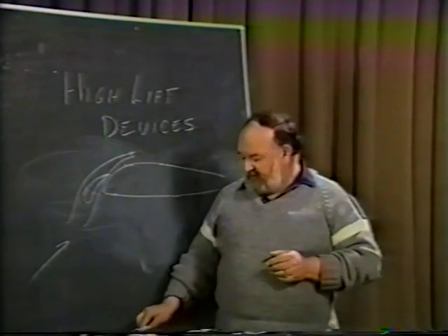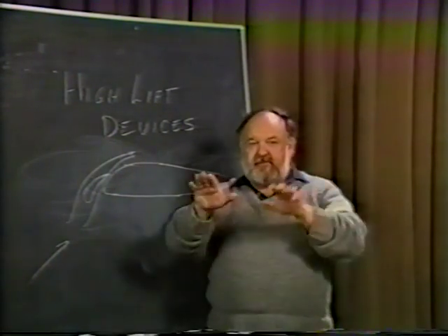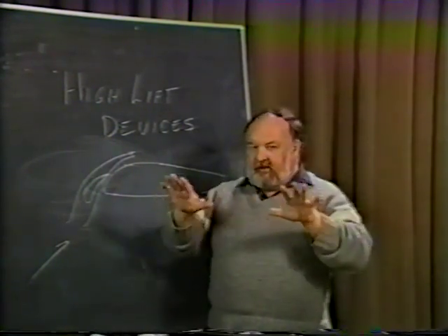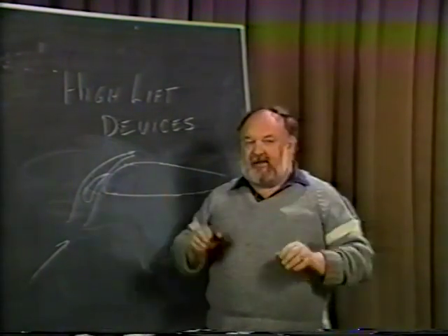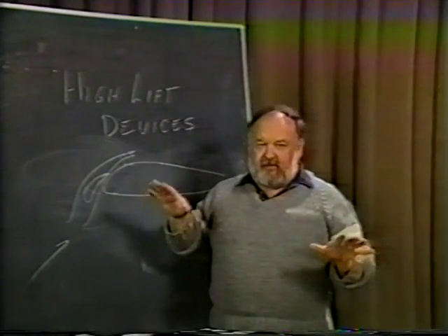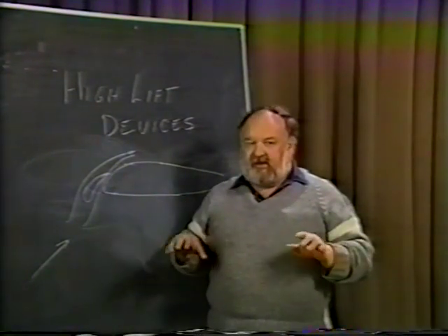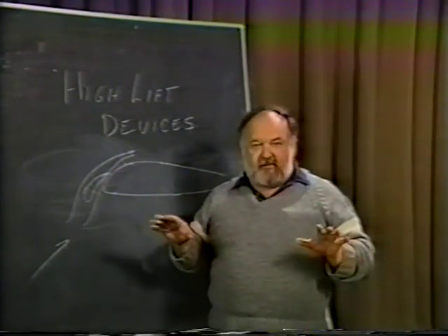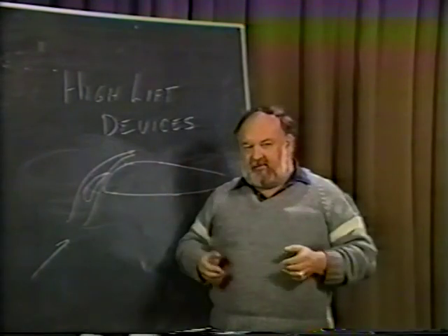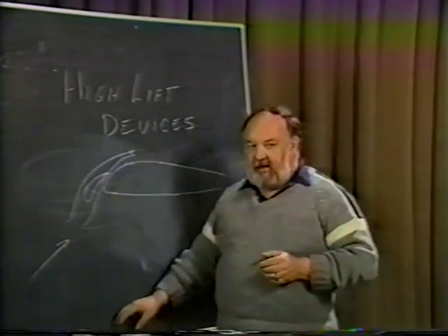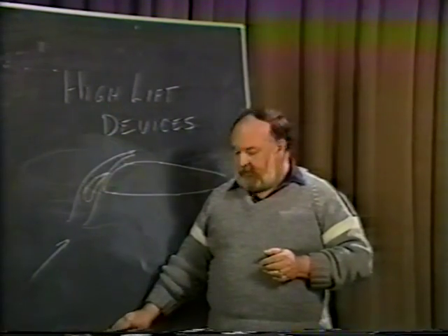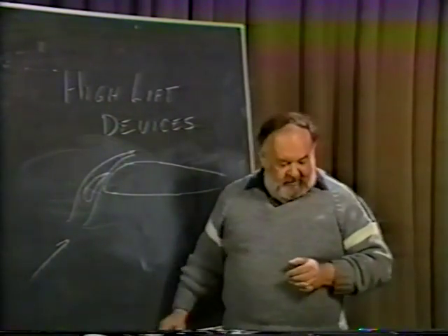And I don't know how many of you have ever flown in a Helio Courier, but as you get it up near stall, you can actually see, you'll be sitting there, one slot will open and close, and they'll move back and forth if you're right on the edge. Has no adverse effect on the airplane trying to roll around. It doesn't change the lift coefficient or the angle of attack or anything else. It's really quite nice to see the way they will go in and out in that particular manner. That's a very common and very nice method of incorporating a high-lift device.